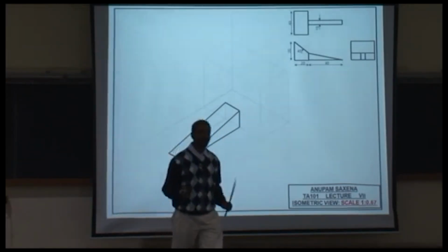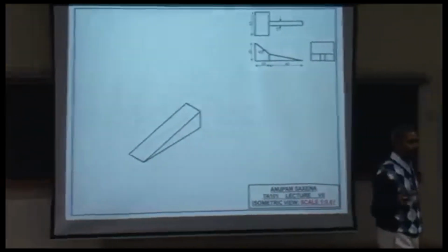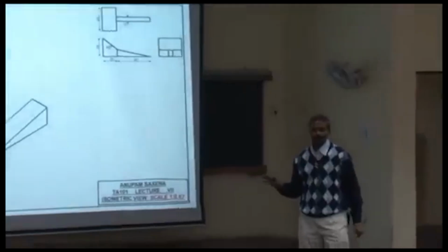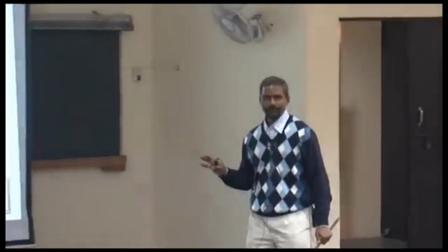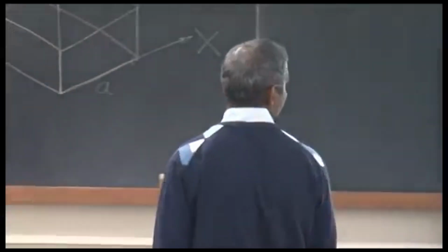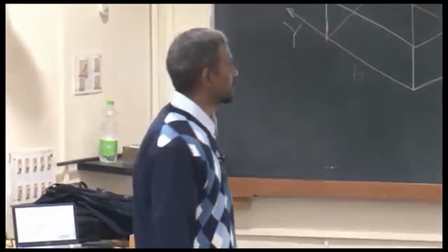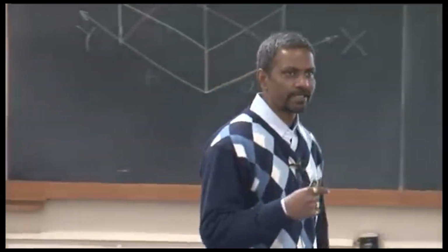You draw the isometric drawing or the isometric view the way you see it. No hidden lines. Okay? Absolutely no hidden lines. How about the sliced block at the back of the rib? Do you see this edge? Yes. Do you see this one? Yes. So you would see that edge only partially, not completely.